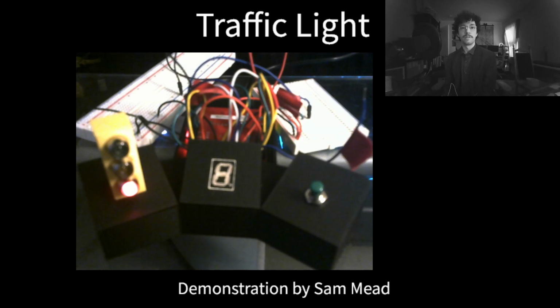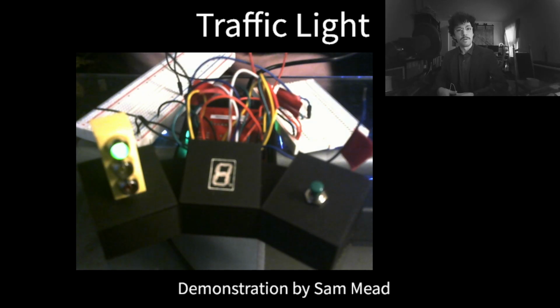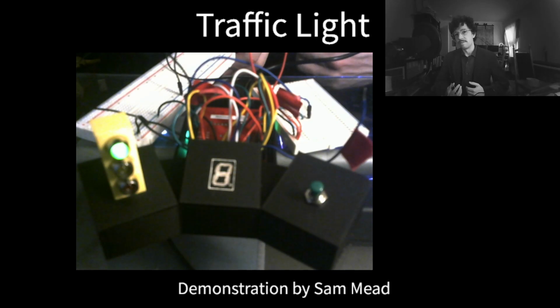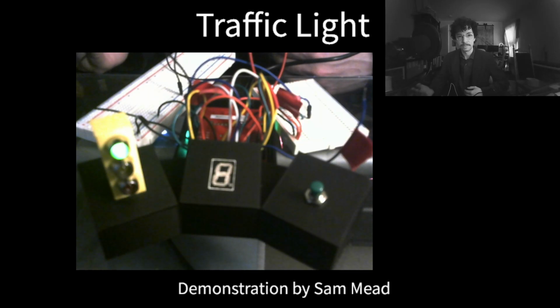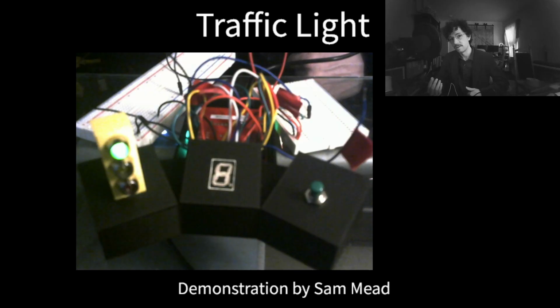So we have a wait 10 milliseconds subroutine within the SysTick file, which we can multiply by what would, in an actual interrupt, be a reload value. So it's just a constant. Like for the green light, we need to multiply 10 milliseconds by 300 in order to get 30 seconds, and by 100 in the yellow and red in order to get 10 seconds.